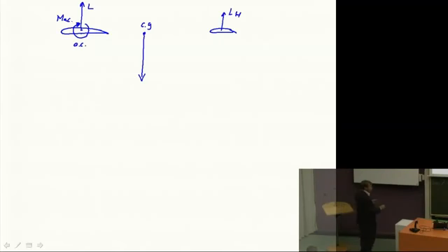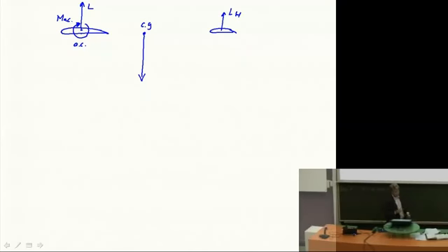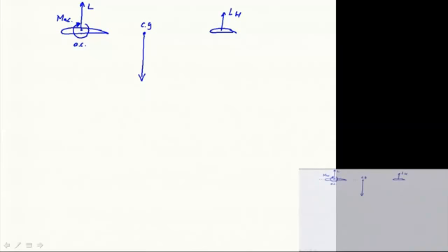So all of this is aimed at seeing what happens when we change the angle of attack, and that's to choose a convenient point. We choose the aerodynamic center. An important definition: the aerodynamic center is the point where the aerodynamic moment does not change as a result of a change of angle of attack. In other words, dMac d alpha is 0.